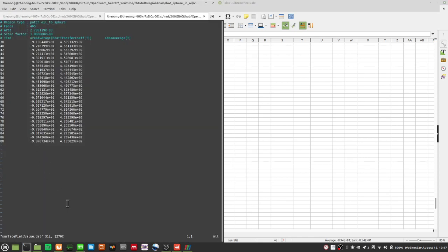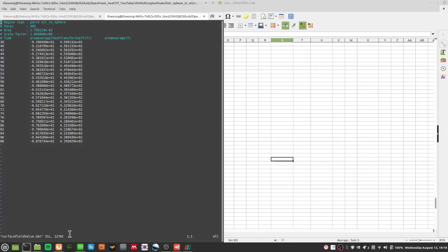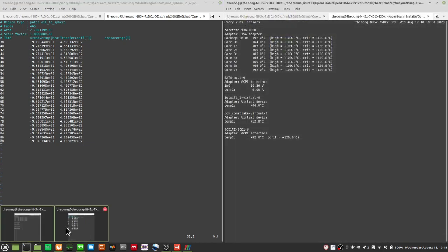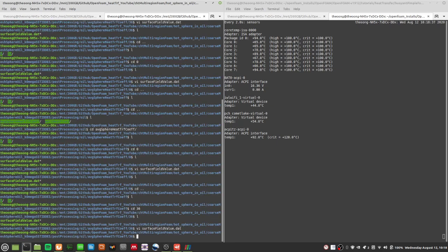So you can see that the model actually helps increase the heat transfer coefficient artificially, but anything beyond the 12-ish seconds at this kind of temperature, you won't expect to have as much turbulence, and the mesh is so coarse that you're not modeling it right anyway. Of course you should be able to run a fine mesh version as long as your time step is forgiving enough so as not to introduce all these numerical errors. So this is just some comparison for you to take a look at.